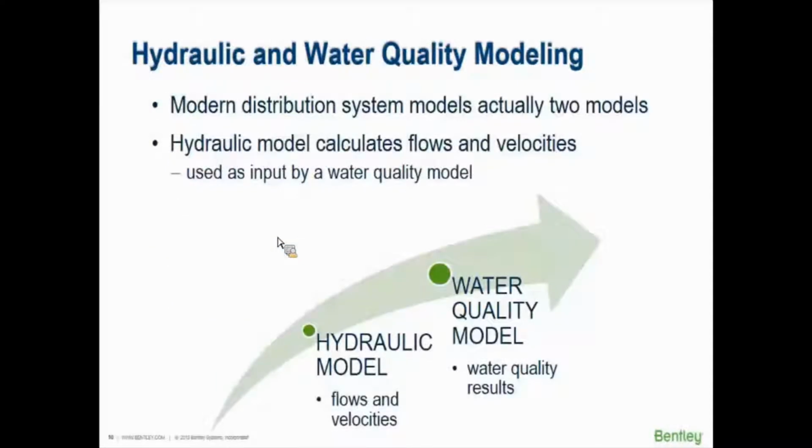Just want to try and differentiate the two here for you. The hydraulic model is really the first piece of the puzzle of a water quality model, and it's imperative that you take that approach to water quality modeling, but you have to get to a good viable hydraulic model first, a well-calibrated extended period simulation model, or you risk deviating from the real-world predictions quite a bit. And this is the workflow for a water quality model.